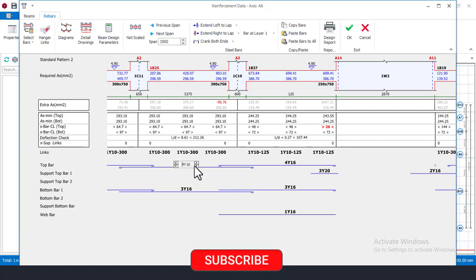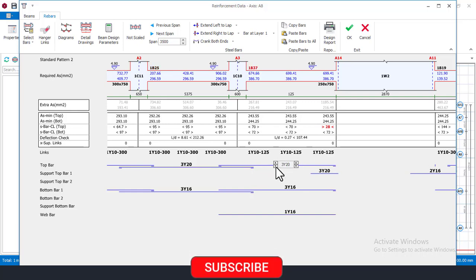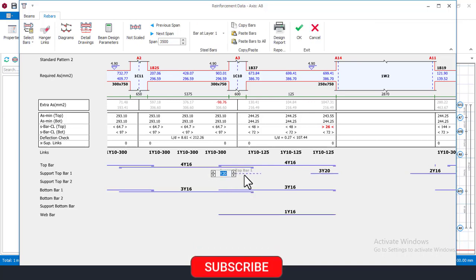Else, I can choose to use Y20, decrease this. You can see that, and then decrease this also Y20 and decrease. But I want to try Y16 first, my beams. So I'll come here right now, increase to 4 Y16, decrease this, and then decrease this first, and then decrease this. Okay, I want to avoid using large diameter bars for my beams, just to save the client's money. So I'll come again right now and then click on this. Now, even when I'm trying to save the client's money, I also put the safety of the structure into consideration. So that's what I'm doing right now.